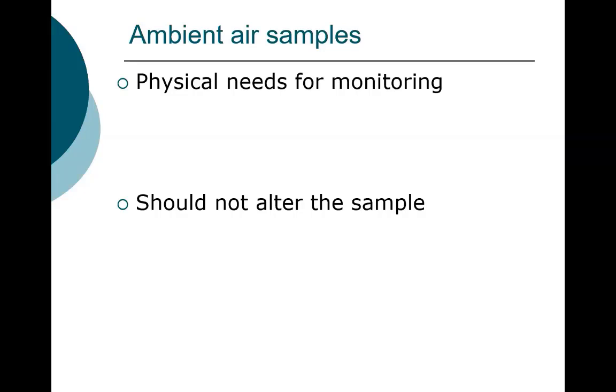There we talked about how in some cases samples are collected in amber bottles, and that's done when your analyte is photoreactive. So in that case you want to make sure you're not sampling in a clear vessel subject to light that would degrade it. For chlorine, we did the chlorine residual lab. Chlorine is photoreactive.